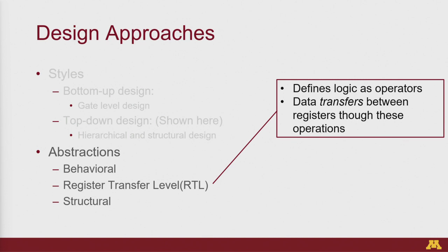When you're processing the information, you would use logical operations. For example, if you want to do an AND gate, you would just say A is equal to B and C, right? Or in the same example, if you want to implement a multiplexer, Verilog has something called a conditional statement, which is another kind of logical operation which implements that. So this is meant to be an intermediate level of abstraction.